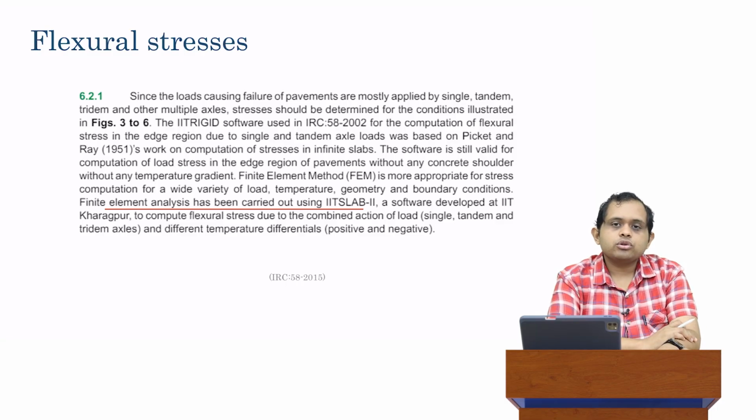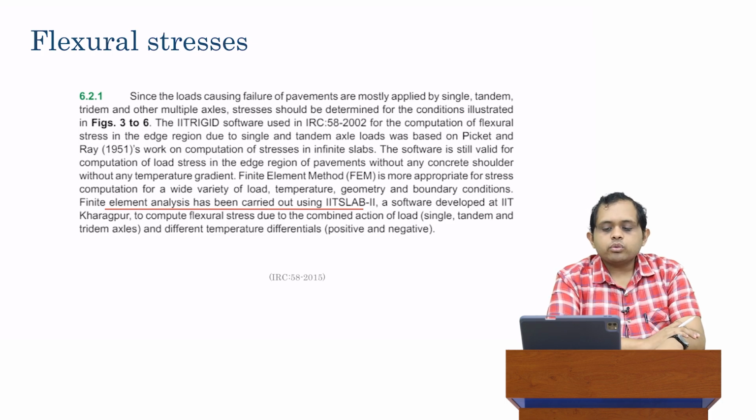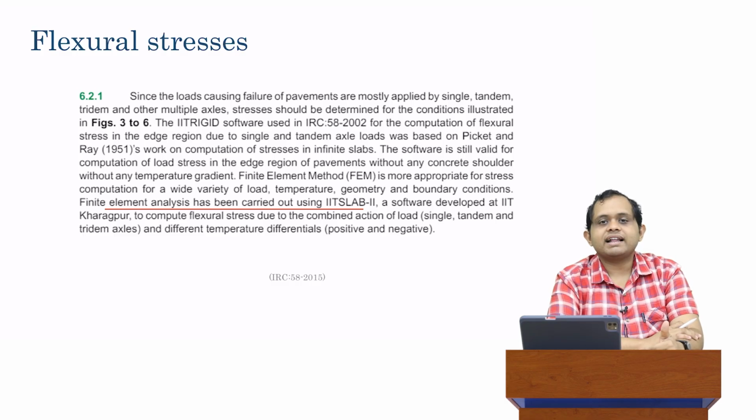But nonetheless, if you want to use those values, we now know what our traffic input is, where to put our critical loads, and the material properties. We also know what value of delta T to use to characterize climate. Now the question is, given all this, how do we finally calculate stresses? Because ultimately, our mechanistic empirical analysis begins by calculating stresses.